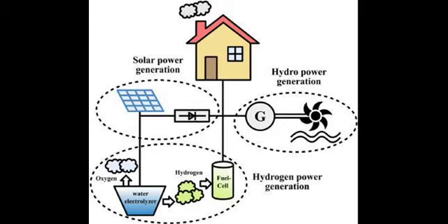For solar and wind energy systems, use the capacity factor, the average actual power output over time divided by the maximum potential output, to determine the appropriate size. For hydropower, consider the flow rate and head to estimate the potential power generation capacity. Sizing for biomass and geothermal systems will depend on the availability and energy content of the feedstocks or resources. Integration and storage. Assess the need for energy storage solutions to address fluctuations in renewable energy generation. Battery storage, pumped hydro storage, or other energy storage technologies can help balance supply and demand.